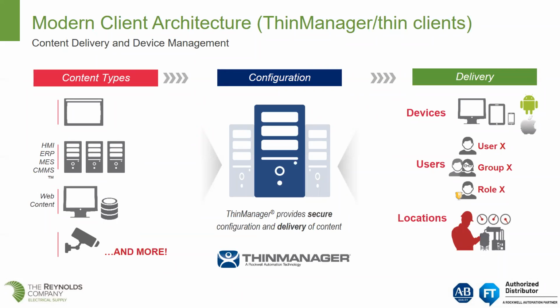As I mentioned, FactoryTalk View SE typically is deployed in a client-server architecture. And so when we consider the clients on the factory floor, today we would look at those clients probably being thin clients so that we don't have operating systems sitting on the factory floor. And Thin Manager is a product that is used to manage the thin clients.